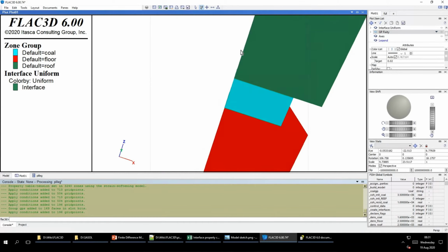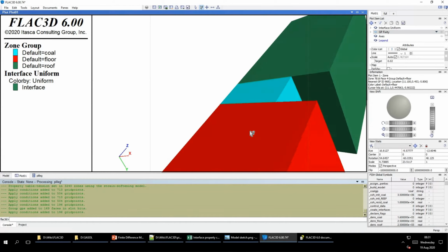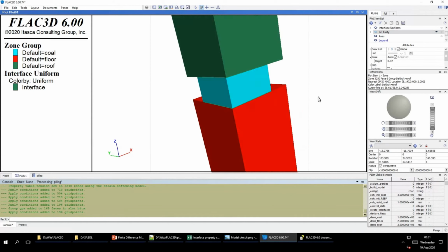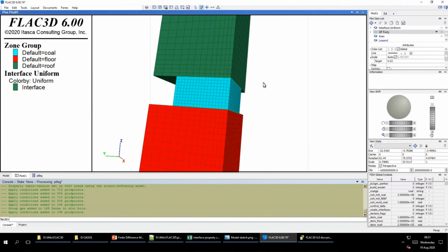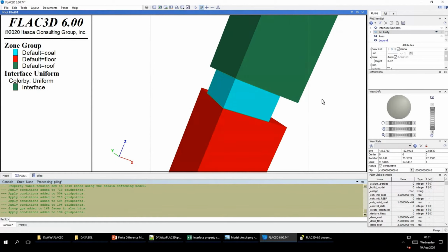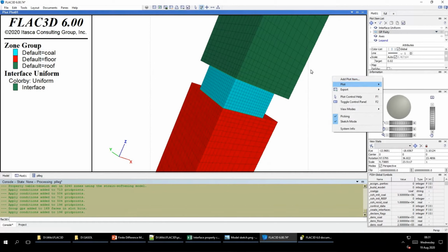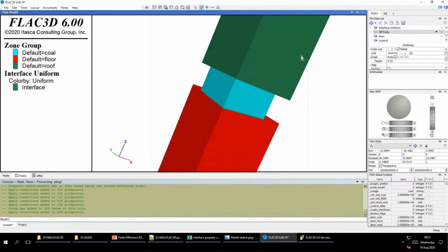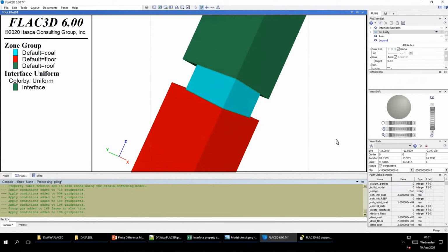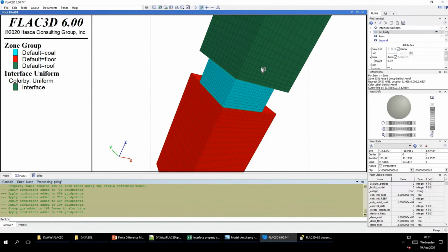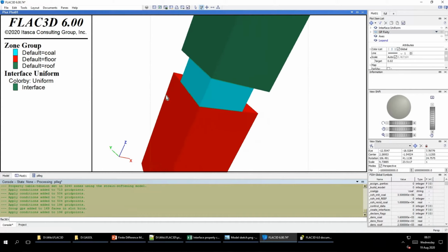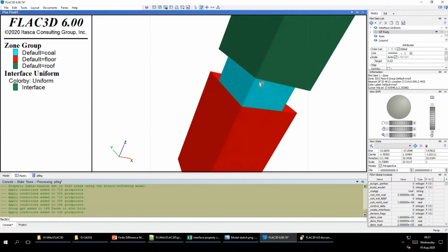Okay, so the rotation is relative, so you can very easily end up in a position where you don't have a convenient view of the thing. It's easy, I suppose, when you're rotating about 0, 0 to get wherever you want. But now I want this thing to be vertical, right? So then you use shift and right click, by the way, pans.